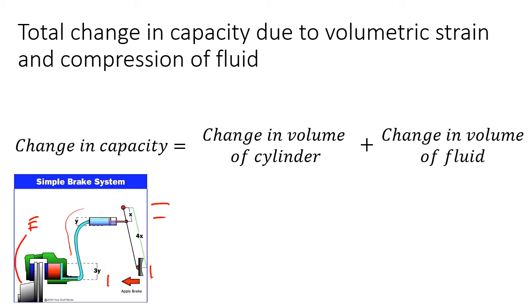So it kind of limits the ratios that we can get in terms of movement of your foot when you apply the brake pedal to the pressure that we can apply on the brake caliper. And if we start to lose some of this volume, so if these cylinders start to expand here and expand here, and the fluid starts to compress, it means that we get less pressure for the amount of movement on the pedal. So it's quite important when we design systems that we take this kind of thing into account.